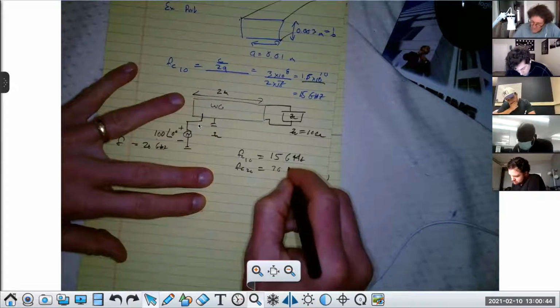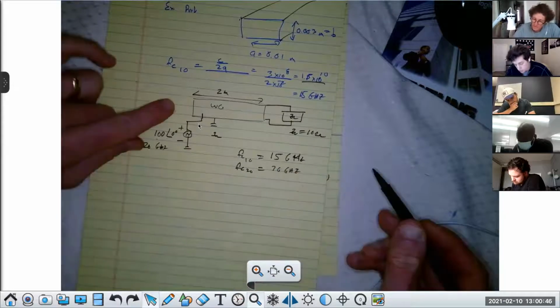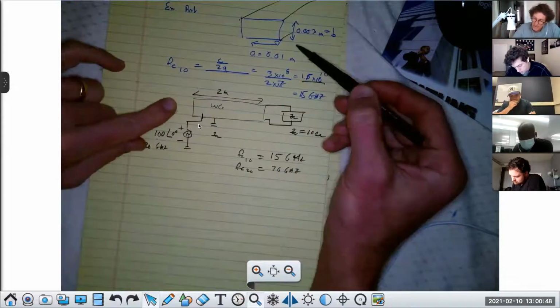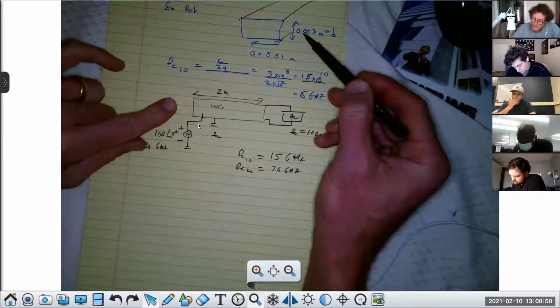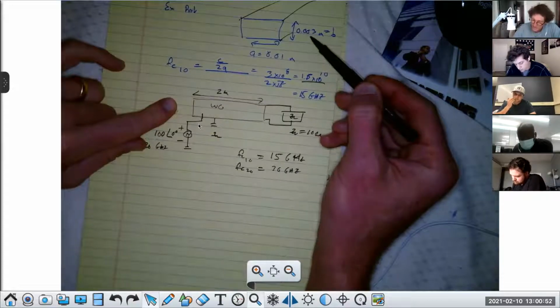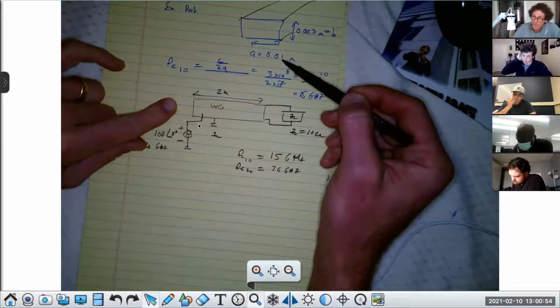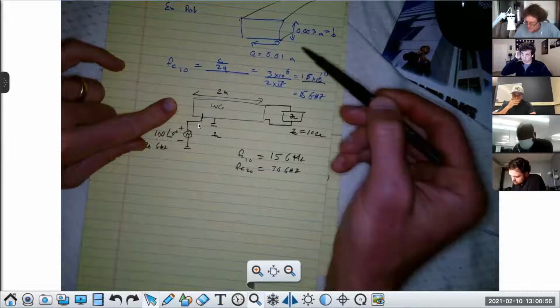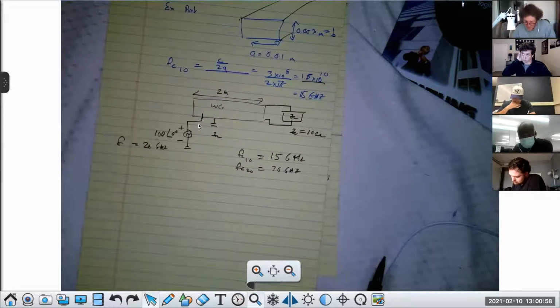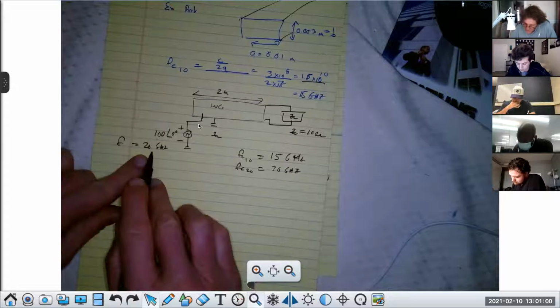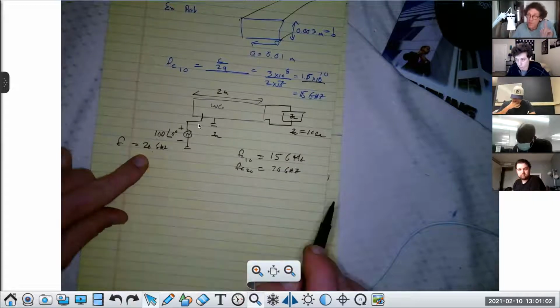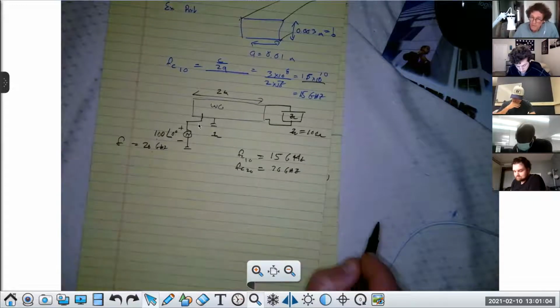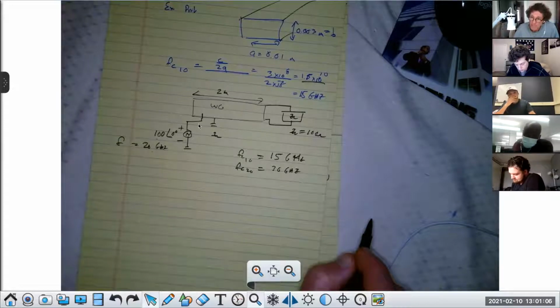If I take the vertical dimension by 2, is A greater than it? Absolutely, right? So it meets the requirement. So that's the 2 mode. I'm at 20 gigahertz, therefore I'm between the first and the second, only one mode propagates. You all agree with that? So only one mode.